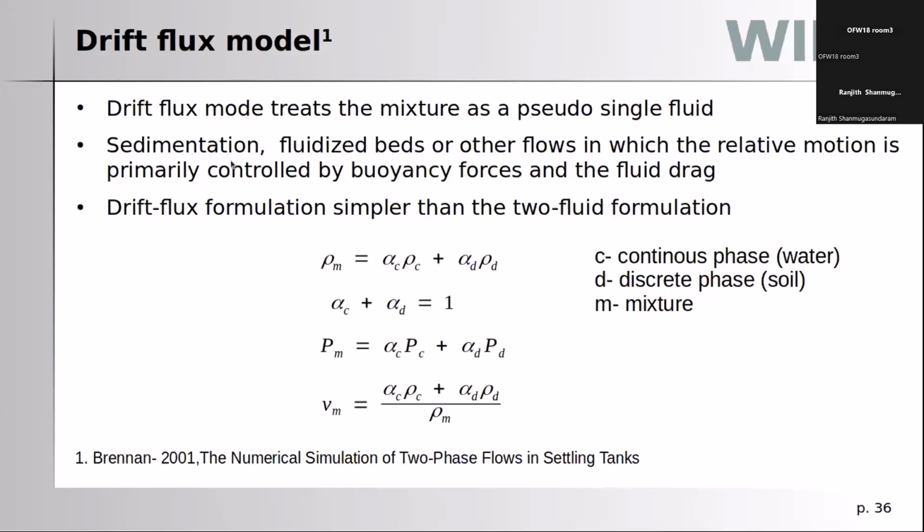And you will have an additional equation for that, which you will see in the next slides. This kind of model is mostly used in the case of sedimentation, fluidized beds, or other flows in which the relative motion is primarily controlled by the buoyancy forces. And the drift flux model is much simpler than the two-fluid formulation.